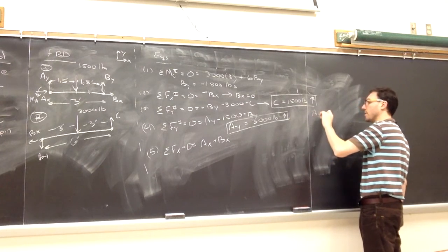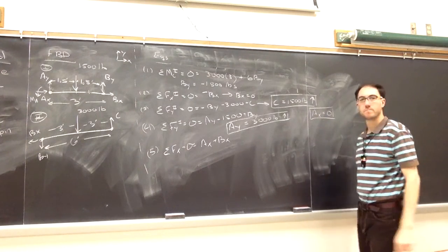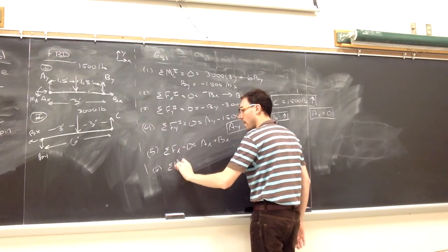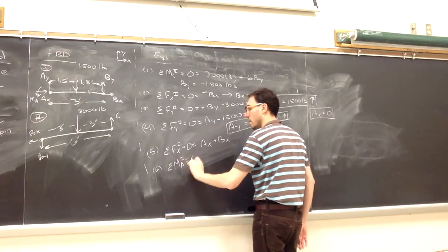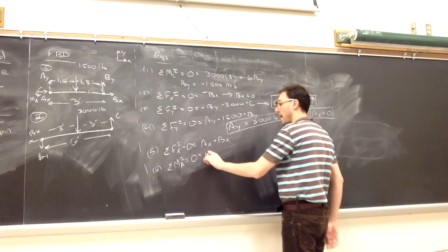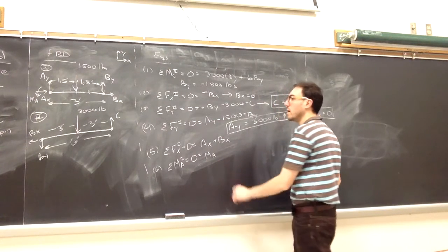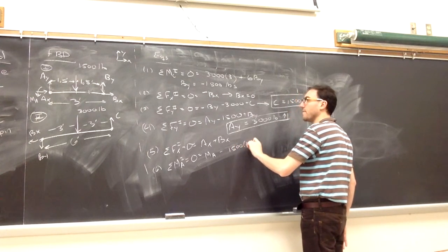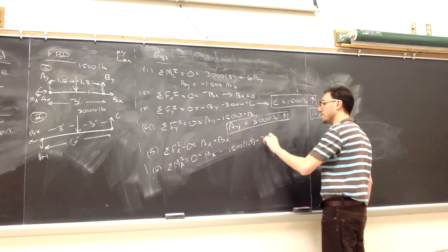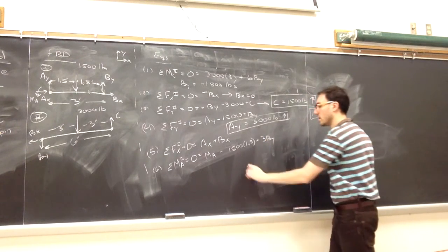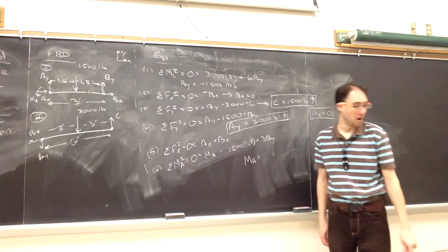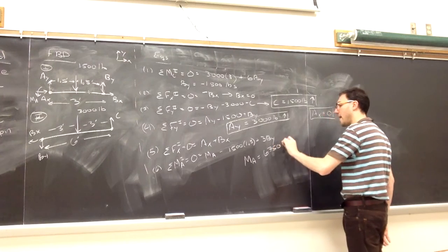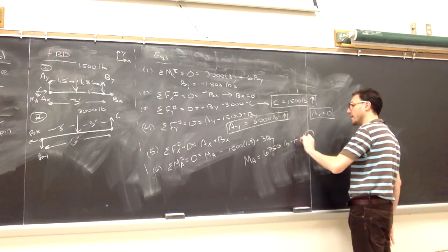So AX must also be 0. And finally, if I take the moments around A in picture 1, I'll have the couple, which I called MA and assumed was positive, minus that 1,500 pounds times 1.5 feet plus 3 times By. So the couple at the wall, to maintain equilibrium, I get a positive 6750 pound-feet. So it is indeed counterclockwise.